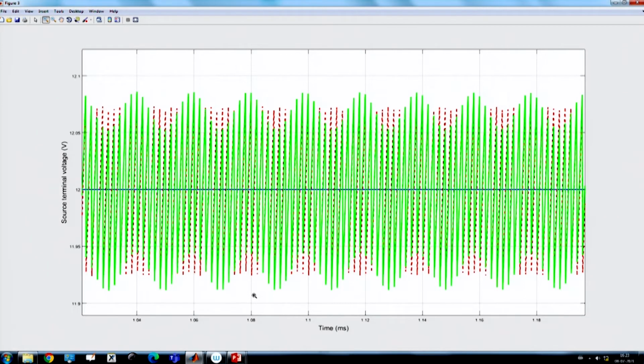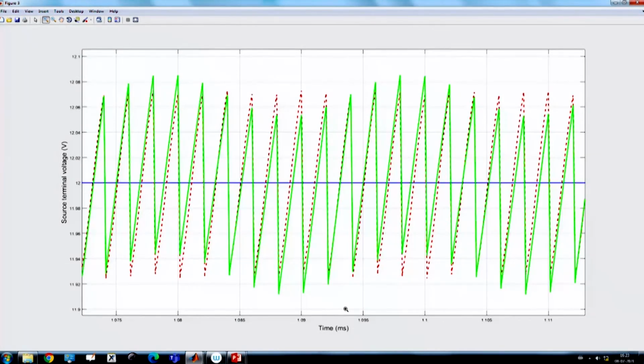So, that means we have to be very careful when we are connecting a power supply for running a buck converter. Our buck converter should be attached very close to the power supply, and if the length of the cable is too long, then that may introduce an inductive effect, and that can create a lot of problems in the converter because it is a switching converter. So, L di/dt will increase and the oscillating behavior will also come.